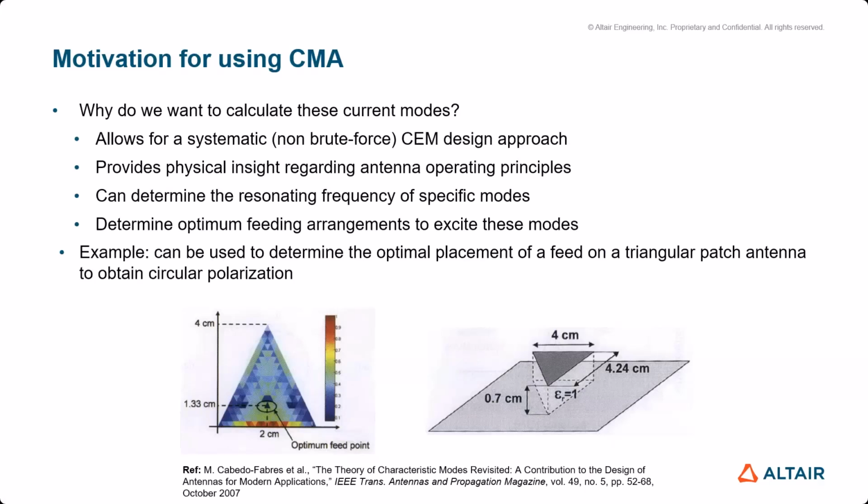Why would we want to calculate these current modes? This allows for a systematic and non-brute force design process. It also provides us with physical insights into the operating principles of our structure or our antenna, and it helps us to determine the resonating frequency of specific modes, which could then also help us to determine the optimal feeding arrangement to excite those specific modes.